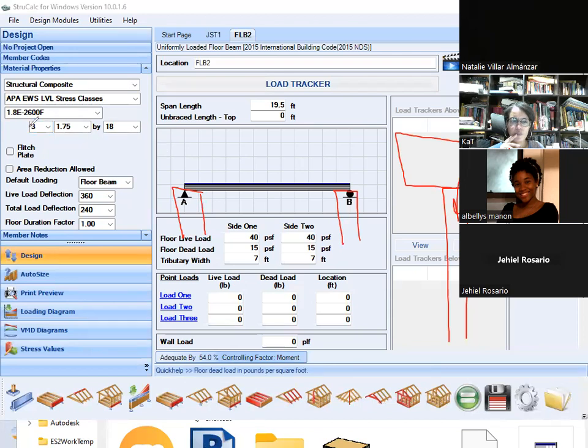So you think of these three layers as 1 3/4, so 1.75 plus 1.75 plus 1.75. What does that give you? Right, that's already giving you about 5 1/4, and then it's 4 1/2. So that's a regular 2x6 wall. So you could literally put 3 studs right here together, and you could probably support them. Okay, that's really straightforward, very quick.